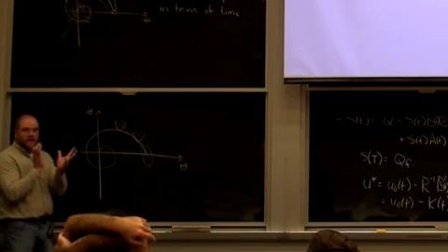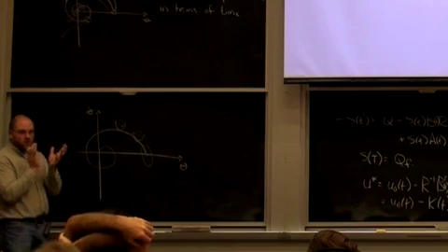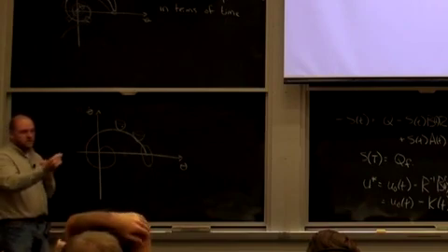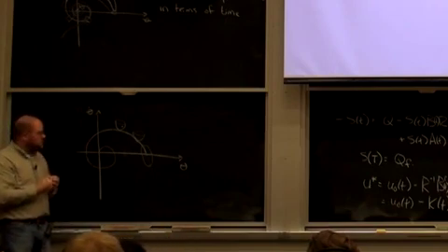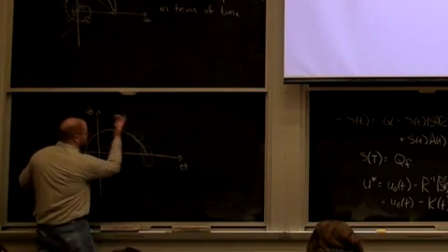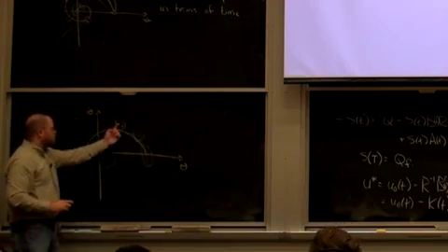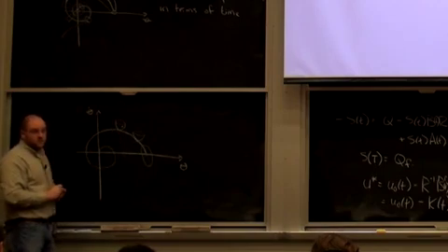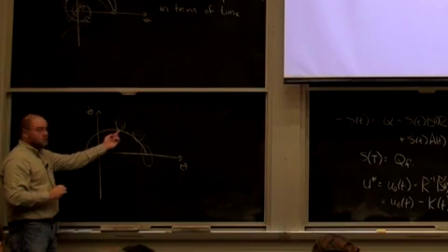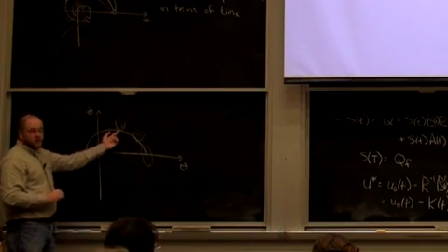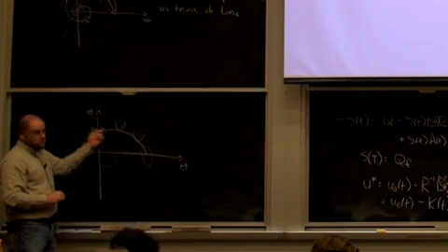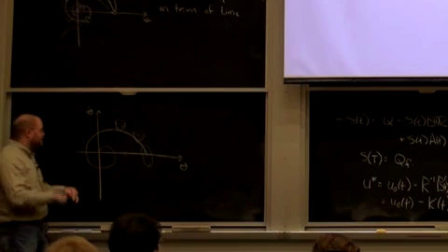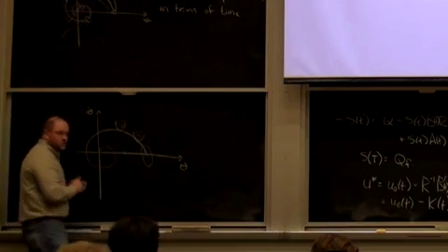Are we okay with the LTI stabilizer being an LQR bowl, or a quadratic bowl? It says the farther I am away in the directions defined by S, I'm going to incur some cost getting back. This is just the same thing. It says if I'm at this point on the trajectory, I'm going to incur this cost to go. And the best thing to do, the minimal cost to go, is living right on that trajectory. As a consequence, the optimal controller, which tries to go down the landscape of the cost to go, is going to drive me back to the trajectory.